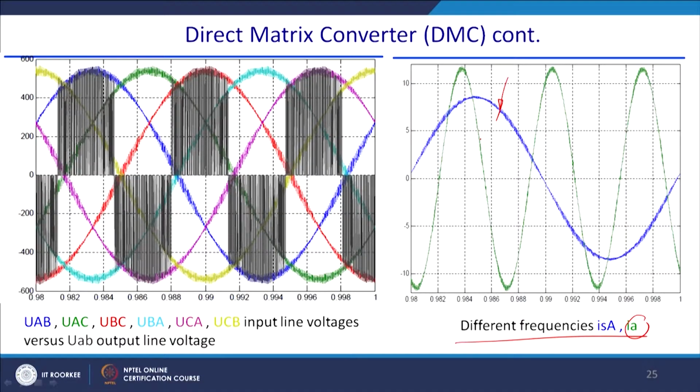Here it is quite applicable, that is a typical wind farm application, where this is the input, and you may have 15 hertz and you are converting into some other frequency, higher frequency in most cases, and you will change it with the help of the matrix converter, and see that it is quite smooth, because of the high switching frequency of the matrix converter. So, this is the application.